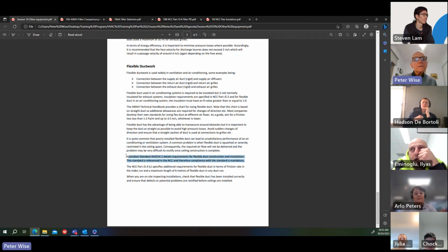There's an Australian standard, AS 4254, on ductwork, parts 1 and 2. Part 1 is for flexible duct, and it details requirements for duct construction and installation. So these standards are worth looking at and getting to know what's in there. It's referenced in the NCC, and therefore compliance with it is mandatory. The duct installers on site probably haven't even heard of AS 4254 Part 1, so it's up to us when we go to site to make sure that they install it correctly.